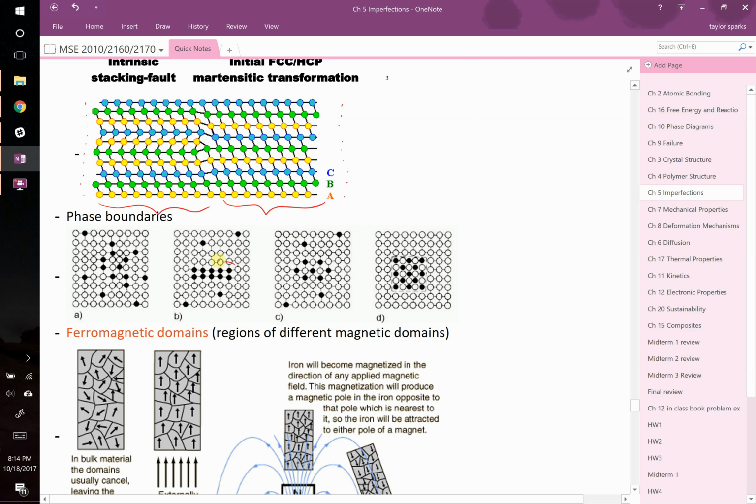So you see here that these atoms have segregated to a different lattice, and it actually has a slightly smaller lattice constant than the white atoms, right? They can also be organized. So for example, in this case, you see that the black and the white atoms have formed an ordered compound, and the lattice parameter more or less matches the lattice parameter of just the pure white atoms. And again, the more mismatch along these boundaries, the bigger the energy penalty associated with it.